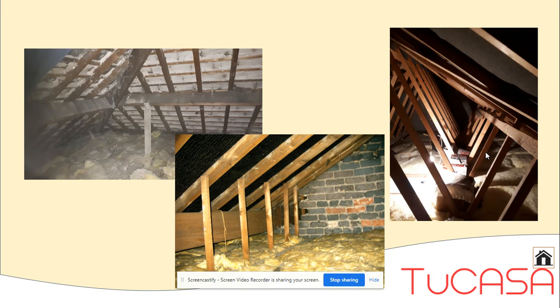The photographs of some properties show you in the roof space the arrangement of the purlin supported on the hip beam here, the underside of the rafters, compared with this section through a truss roof. It's only a partial view, I'm afraid, because truss roofs tend to be rather cluttered. It's very difficult to take photographs in there, but I hope you can tell the difference between the engineered solution of the roof truss in our properties nowadays, as opposed to the older assembly of rafters and purlins.